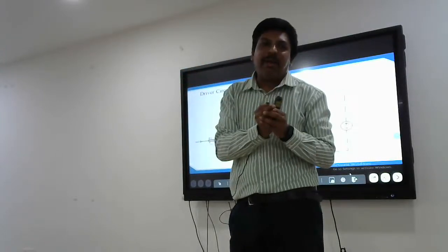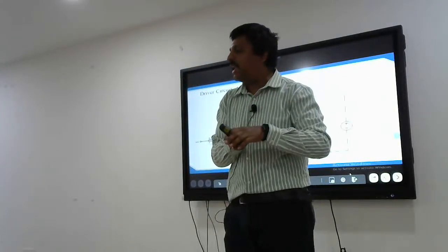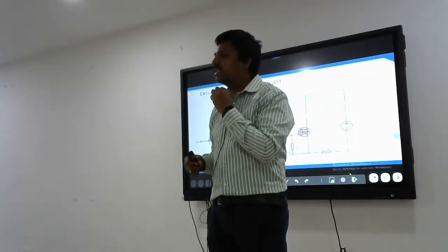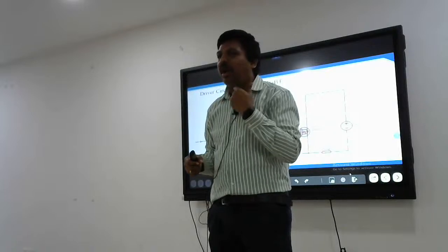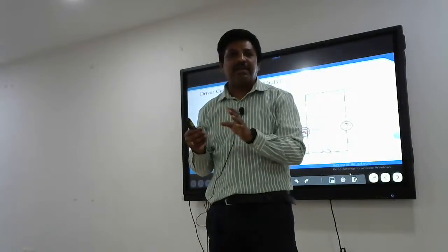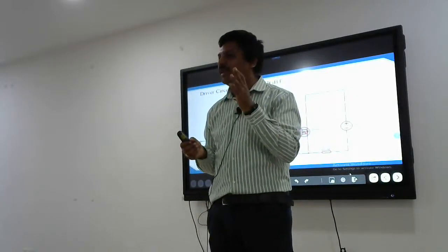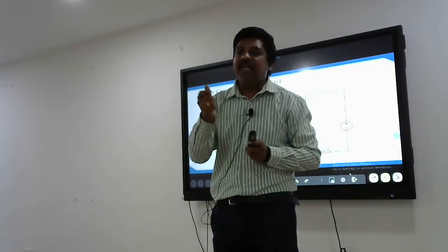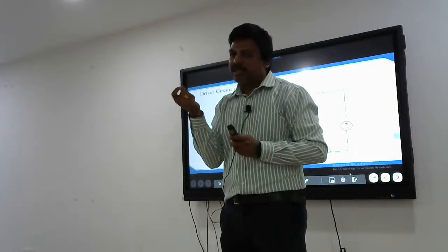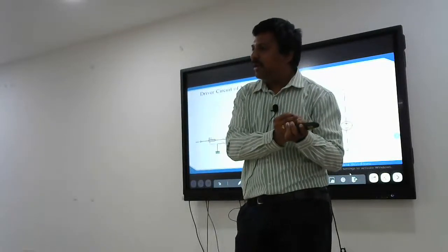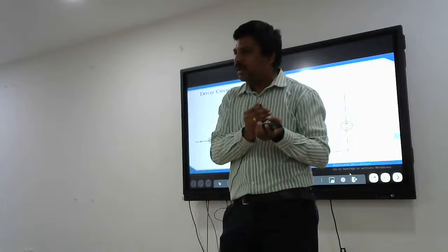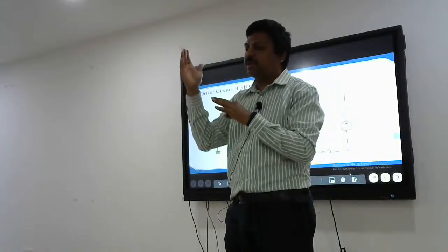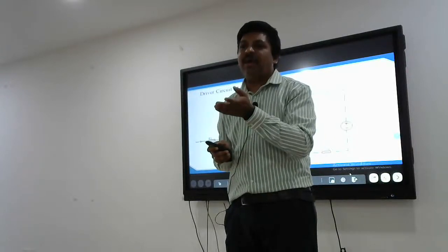Control circuits are operated at lower voltage, like 3.3 V. Control can be done by either digital means of generating the control PWM or analog means of generating the control PWM. So don't always go for direct programming of microcontrollers, DSpace or FPGA. Some applications require something very small, even a 555 timer and a simple operational amplifier. Operational amplifiers we can use, or we can use digital microcontrollers like the Arduino Nano. But where we are using it is very important.